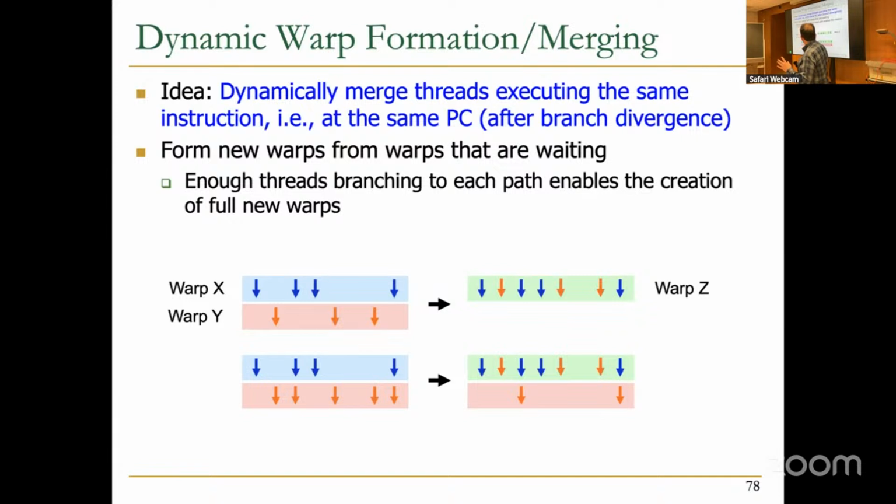But here, that's not lockstep actually. Lockstep comes from the fact that in one warp, all of the threads need to finish the instruction that you are doing. But they already finished that branch instruction, so that's not related to them remerging with something else. They can continue that path, and the one that was left over can be remerged with something else. Exactly.